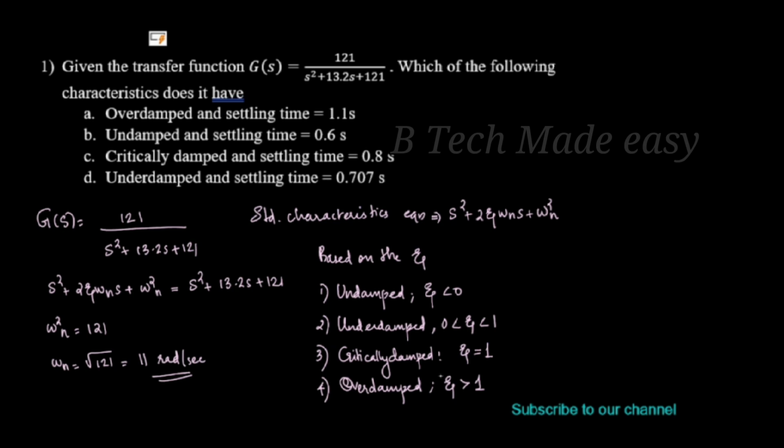So, the next step is we have to find the value of damping ratio or zeta to determine whether the system is undamped, underdamped, critically damped or overdamped. For this, we have to compare the coefficient of s. That means 2ζωn is equal to 13.2. We know that the value of ωn is equal to 11, so 2 into ζ into 11 is equal to 13.2.